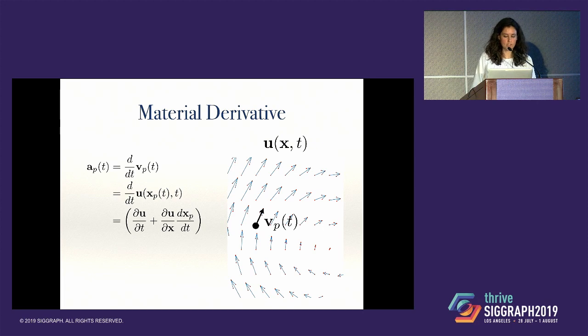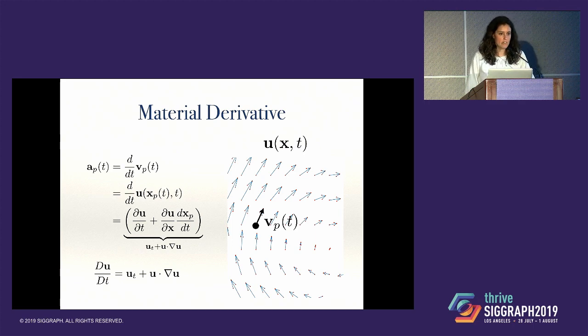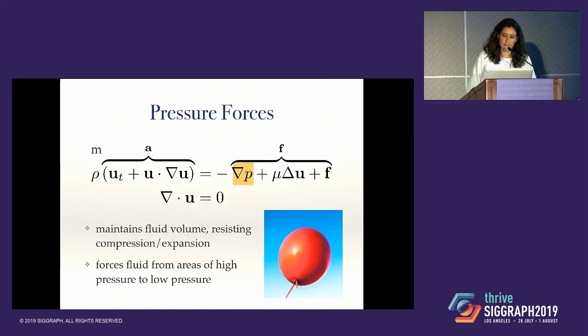So to differentiate u, we have to differentiate with respect to the second component, so that's du dt. And then with respect to the first component, we apply the chain rule, du dx, and then dx dt. And that dx dt is just that velocity again, and so we get this expression. So really, this kind of complicated looking derivative is just the acceleration of a particle moving through the flow at that point. This is called the material derivative, or the substantial derivative. It has a lot of different names. Material derivative is one of the most common ones. Also particle derivative. Okay, so that explains that term.